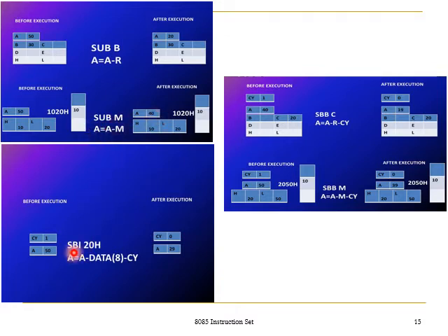Next is subtract immediate, the given 8-bit data. So whatever 8-bit data we give over here is subtracted from the accumulator content, right? You assume that the carry flag is set before the execution. After the execution, it will take this 50 and the immediate data the user has specified over here, and it is going to subtract these two things.